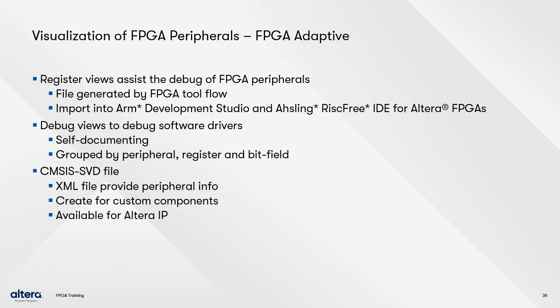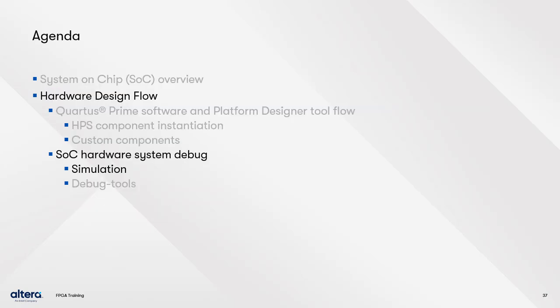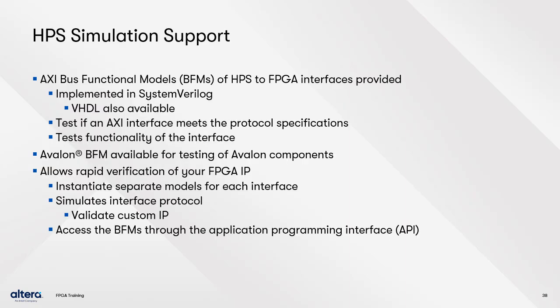easy debug. Now that we understand Quartus Prime software and Platform Designer tool flow, let's look at SoC hardware system debug. We'll start with functional simulation. To make verification of custom IPs easy, Platform Designer supports bus functional models for both AXI and Avalon interfaces.